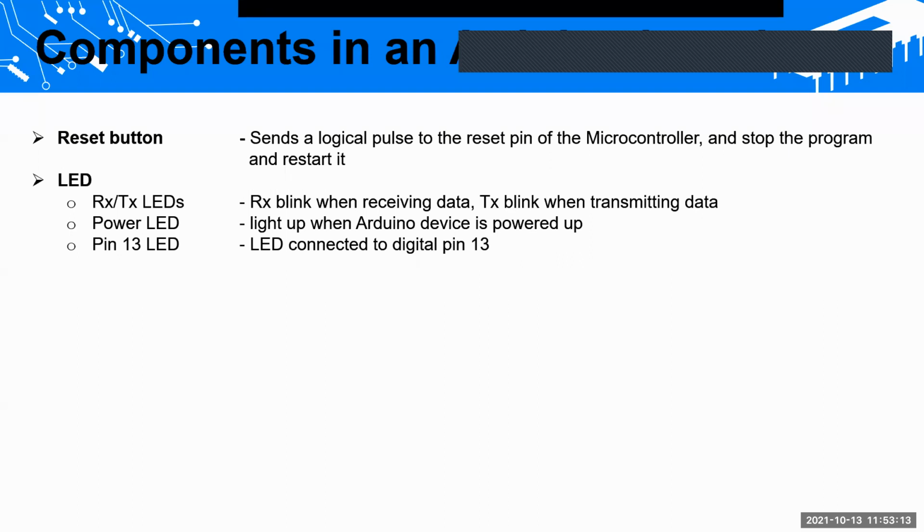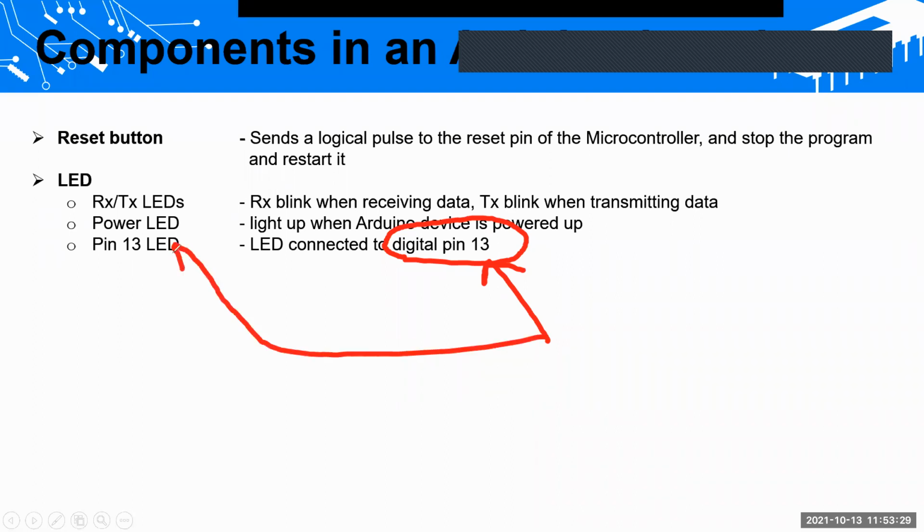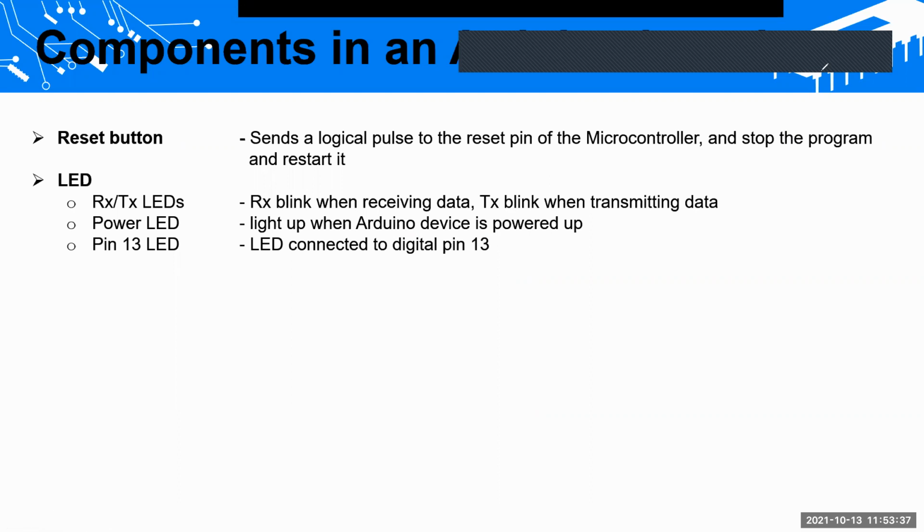Then we have another LED called the pin 13 LED. That's tied to digital pin 13. If you give 5 volts to this digital pin, this pin 13 LED will blink. Most of the time we use that LED to check whether the Arduino board is working fine.